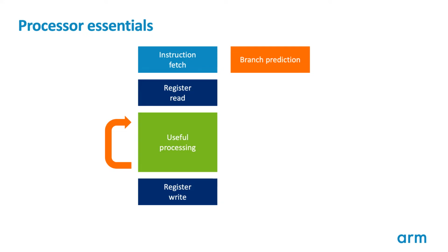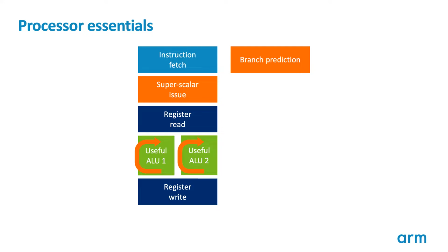Most instruction streams have fine-grained parallelism in them, instructions which can run in parallel as they have no data dependency. This allows us to increase performance by doing multiple things in parallel. The downside is that instruction sets are generally specified as a serial instruction stream, so we need to add some additional hardware to manage the parallel instruction issue.